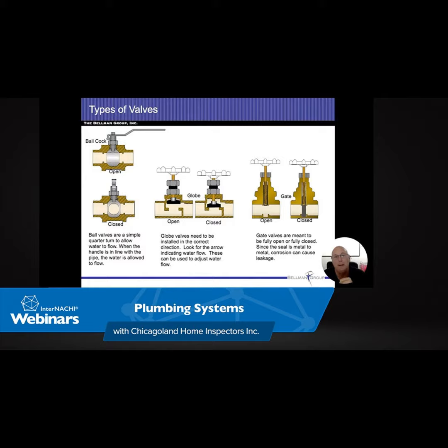If you are taking notes, and I hope you are, these numbers that are written here in that box are important. You definitely want to get those written down. So 3 feet above a window, 12 feet from doors and windows if it's on the same level. All right. 6 feet from the property line, 7 feet above a deck, and 7 feet above the ground. All right. So if I have a deck on this roof, it has to be 7 feet higher.